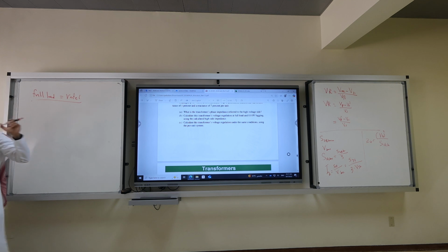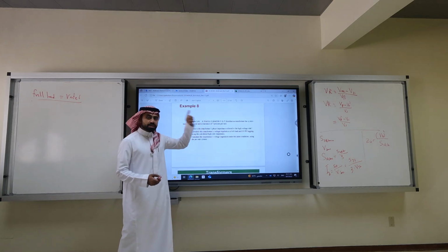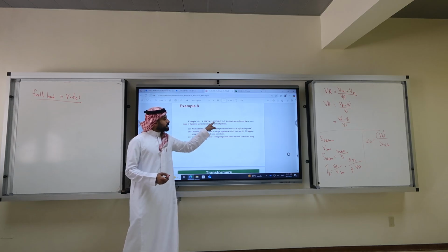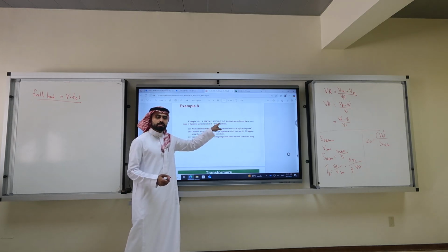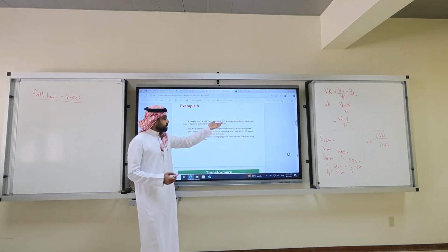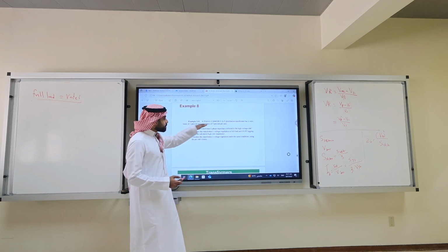Okay? What is rated? From this question, we have apparent power is rated. Delta Y, we told you this is delta, this is Y, 208. It means the coil is 208 divided by square root of 3. This is full load. 1%, 7%, it doesn't matter.